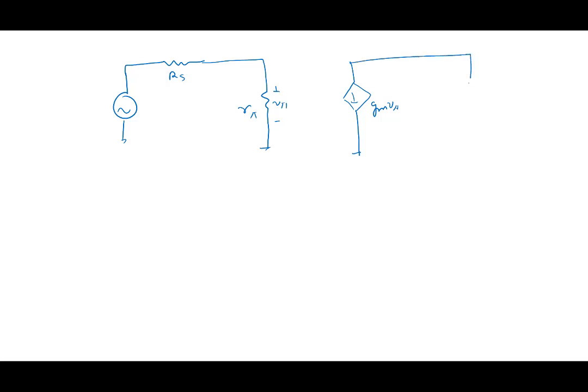So we have a circuit like this. Rs, and we have a circuit like this, rπ, and we had here gm Vπ, this plus minus Vπ, and we had here RC, and we were wanting to find out what is the effective capacitance seen by Cμ.